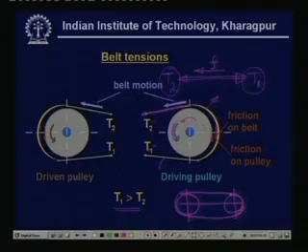You can see in the exaggerated figure that obviously the angle of wrap is decreasing, thereby the power transmission capacity will be decreasing. So, please keep in mind that whenever you are trying to design a belt drive, always keep the tight side on the lower side, and the slack side on the upper surface.